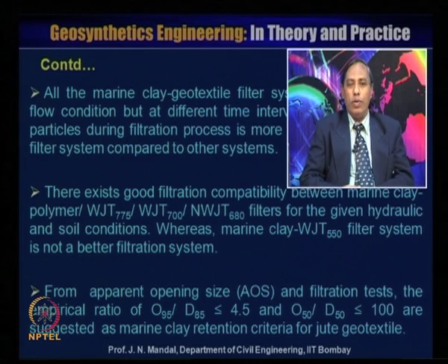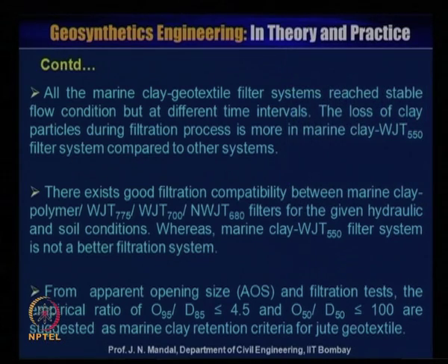From the apparent opening size or AOS and the filtration test, the empirical ratios of O95 by D85 less than or equal to 4.5 and O50 by D50 less than or equal to 100 are suggested as marine clay retention criteria for jute geotextile.